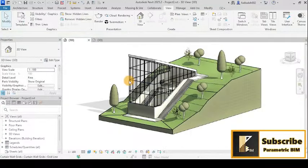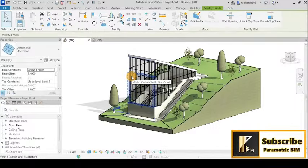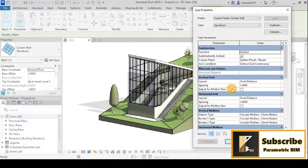If I select this curtain wall and come here to edit type, and for example the spacing between these mullions, maybe I change it for the vertical grid to 2 meter, or let's say 2.4, like the horizontal spacing, and apply it.